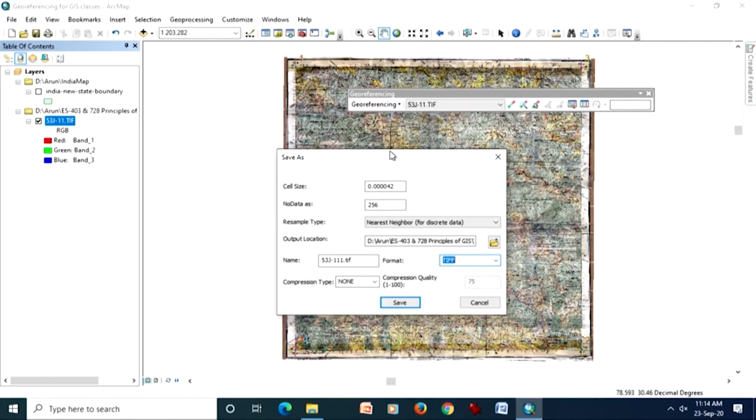So I can go for the next step without much problem. But if you want very accurate georeferencing, then you can collect a few more points, but especially one should collect in the center. Corner points have already been selected, so it would be better if you select in the center, which will take a lot of time. So I have just chosen first order polynomial.